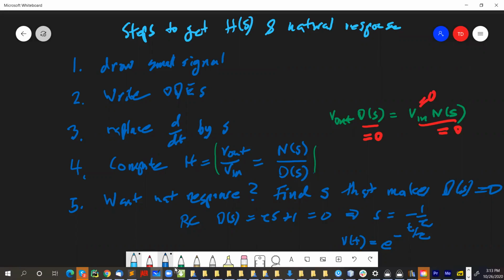In general, for a second order system like an oscillator, hopefully the real part is negative, so it's actually stable, it'll decay. But then it'll tell you how it's ringing, how many cycles it'll ring, what frequency it'll oscillate at, and all kinds of stuff. So it's a really handy method to find the natural responses. And it just reduces down to simple algebra and solving these usually quadratic equations. And we're going to do that later for second order filters.